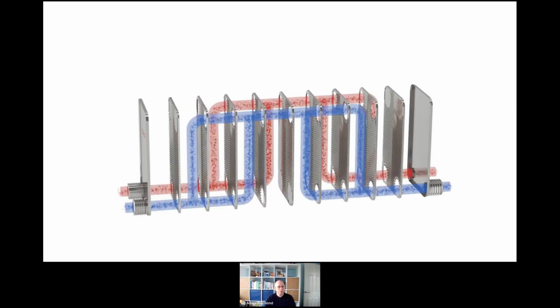Unfortunately, I can't show you the flow animation, which is quite nice, but it gives you an idea of how the flow is going through the heat exchanger and where that extra heat's being transferred. This image here is actually a traditional two-pass heat exchanger. The difference between the two-pass and the two-stage is we have an extra 2 connections at the top on the left-hand side.